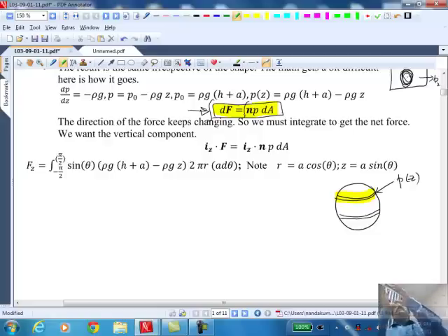Except you're going to replace pressure by the shear force. The beauty about the pressure is it's simple in structure. It has only a normal component, whereas with the shear, you need to worry about which component of the shear you're dealing with. There are 9 components, whereas with pressure there are only 3 components based on the normal. Any questions so far?